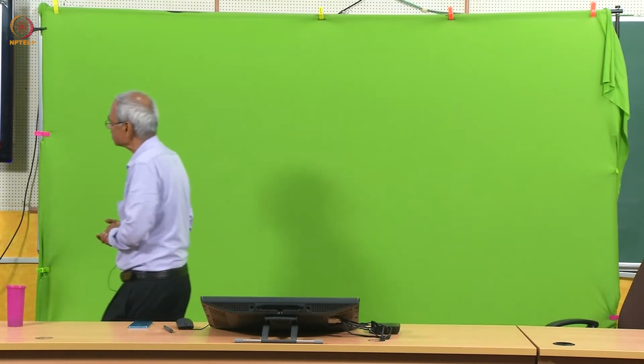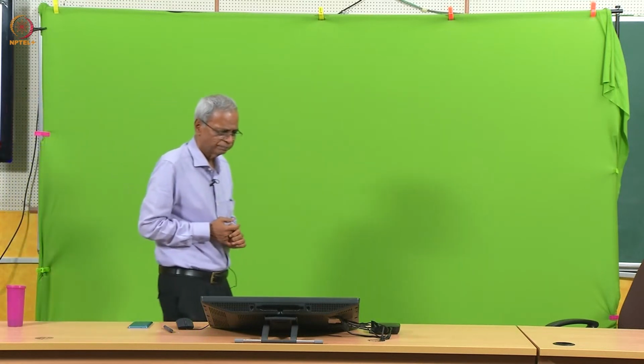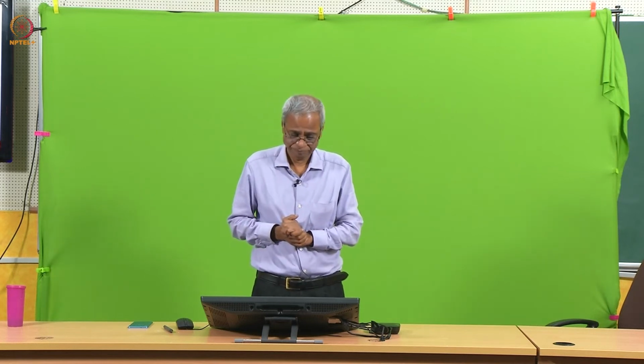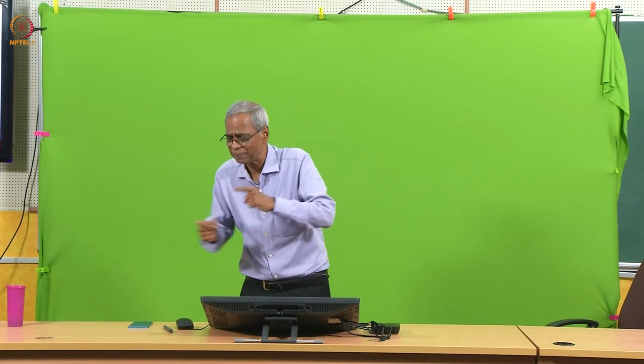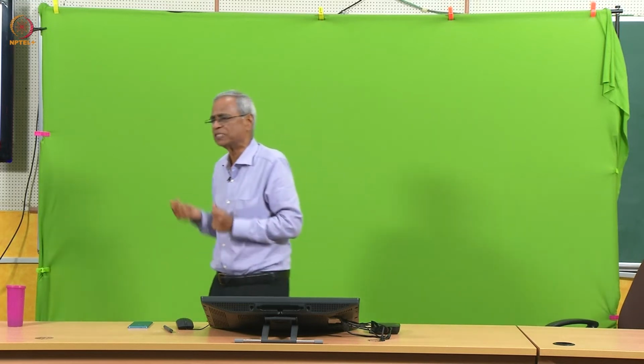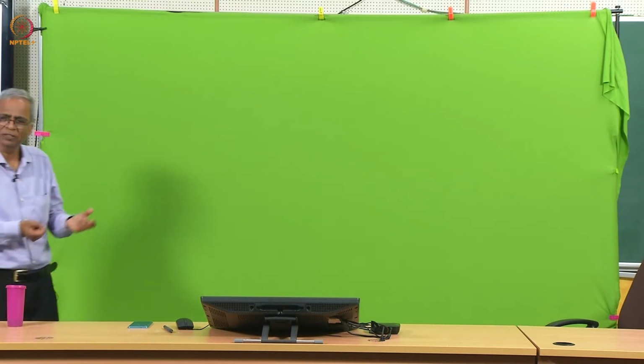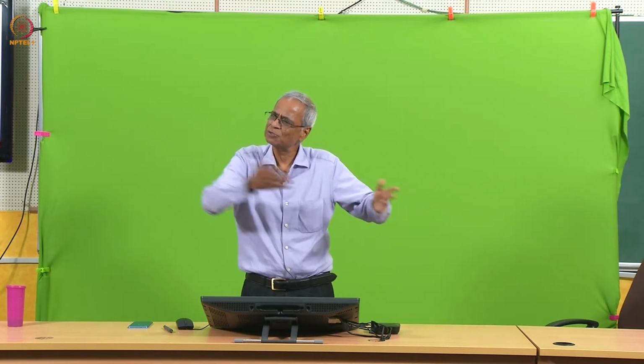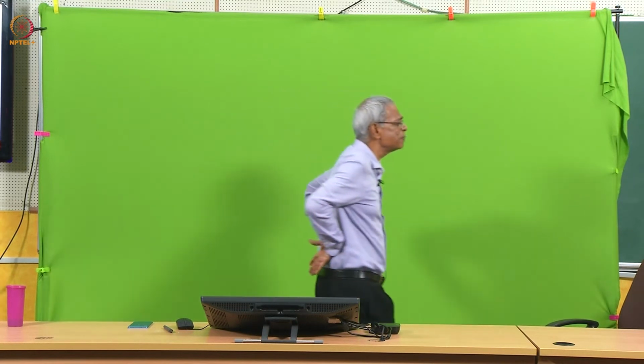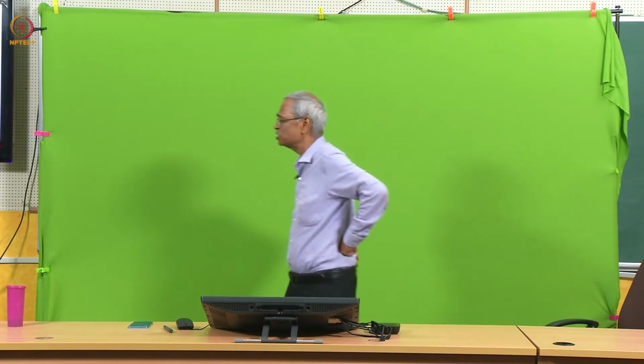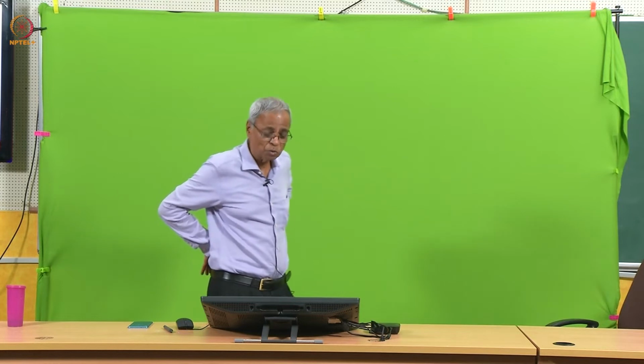The third thing, which I have not emphasized, and will emphasize here, is the electrical management. Something that we learnt the hard way. Very often our smaller batteries have currents of 100 ampere to 200 ampere. When you have such high current, even a milliohm path difference, there are two paths, there are conductors, current can go this side, that side. A milliohm path difference can mean 0.1, 0.2 volt drops. And all these batteries operate with 0.56 volt charge to discharge. You get a totally different picture of what is actually happening. Your strategy for charging, discharging goes for a toss and you can get into serious trouble. So, you need a very good electrical design.